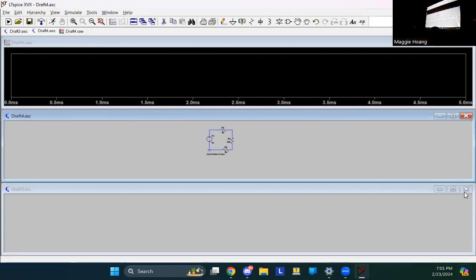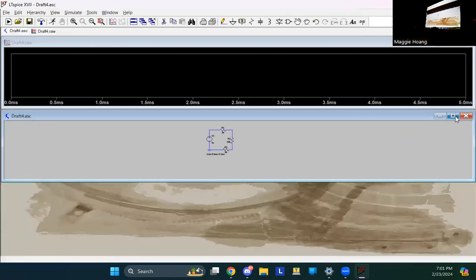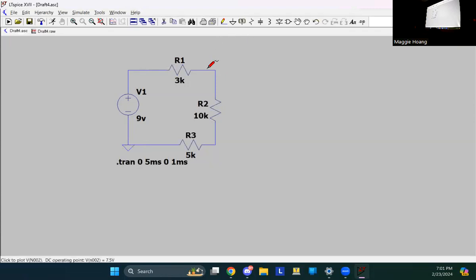Oh, wow. Okay, hold on. So this is where the time is, but we don't really need that. We can just put the probe right here. If I put the reference marker to here, it's gonna give me a negative, I think. This point is going from the reference point. So earlier I explained the node voltages. That's what this is. PSpice does this a little better.